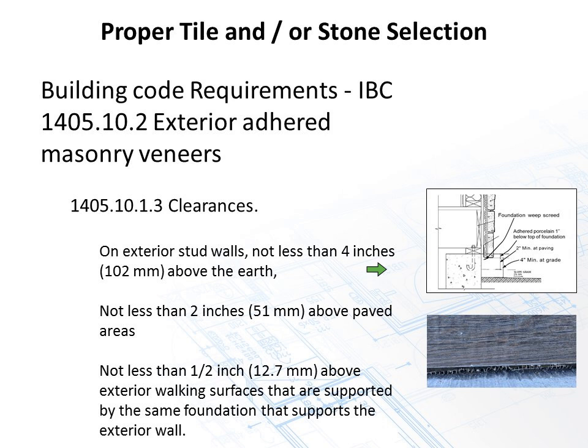Not less than ½ inch above walking surfaces that are supported by the same foundation. So we want to make sure that we don't have water going back in underneath that wall.